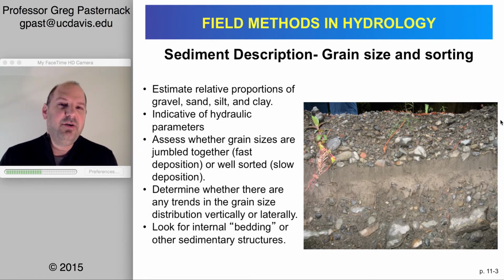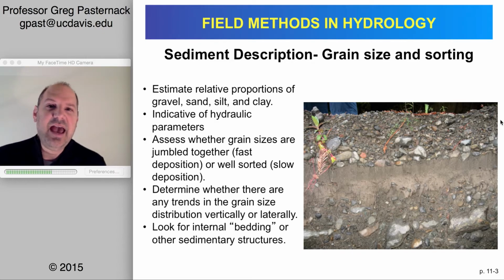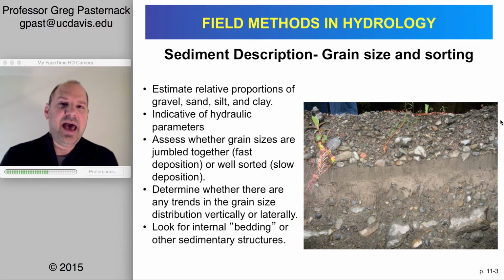We talked about, with the open channel flow, the idea of roughness and Manning's n and the role of grain size in that. But in groundwater flow, we have hydraulic conductivity, and it's largely determined by issues related to particle size or grain shape and sorting. There are other factors, but grain size is usually the simplest and most important factor that people tend to characterize.